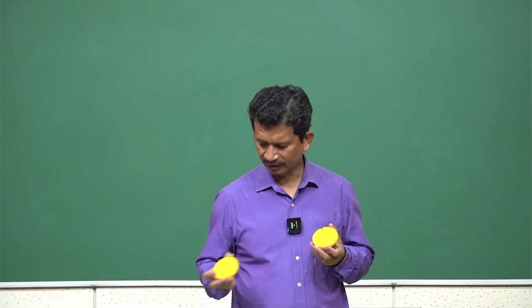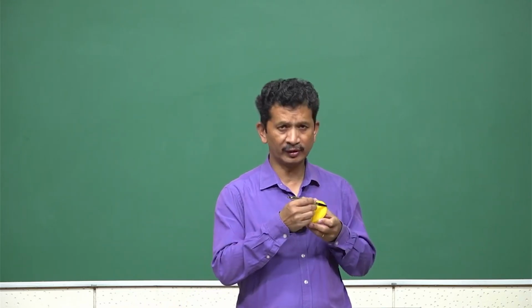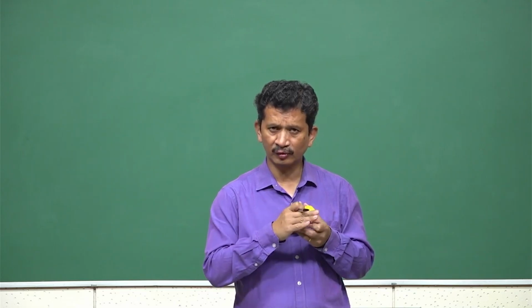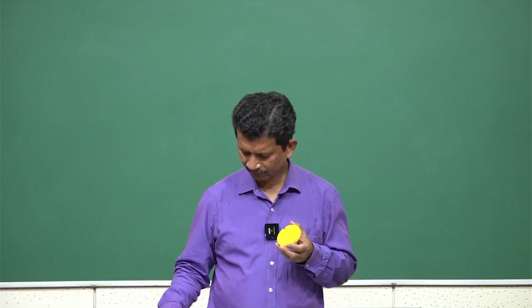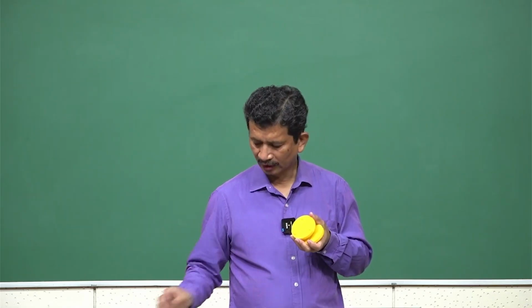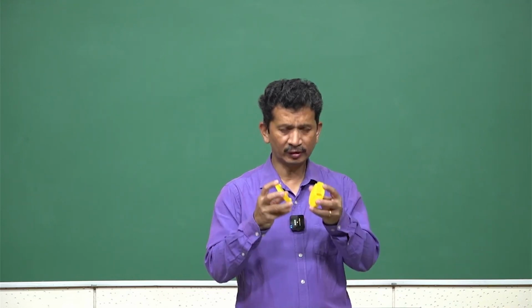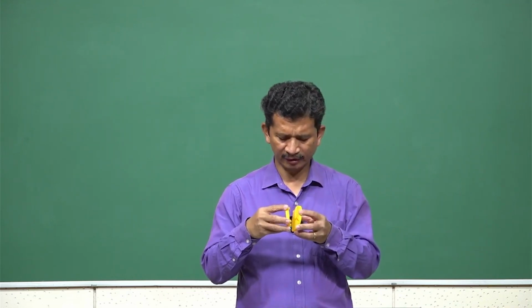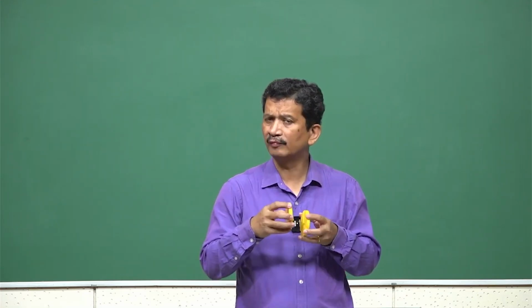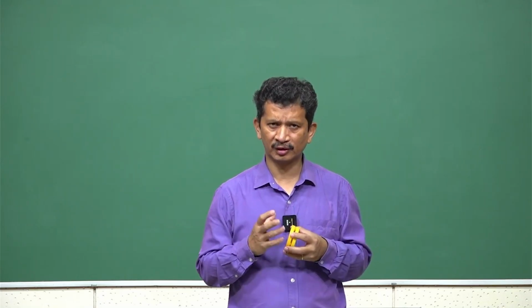So, again I 3D printed this, and what we see here is 3 radial V grooves. They are all intersecting, with all the V grooves on the same surface, and on the other part we have the 3 ball ends. Again here, we can also start with 1 V groove. What we see here is 1 V and the ball, which can always move along that V groove. So, if there is any relative change, it will allow that expansion and contraction.